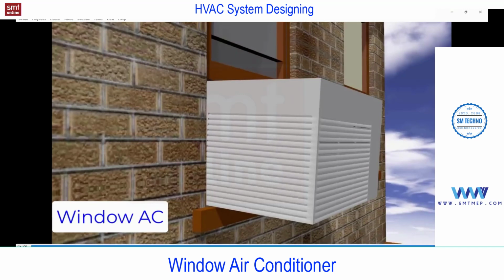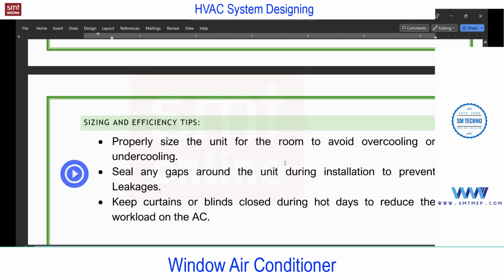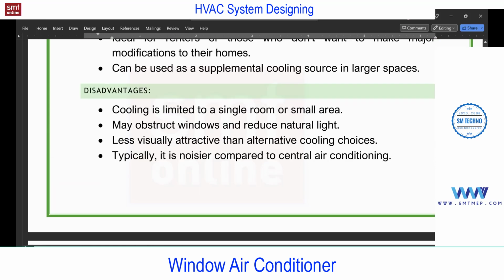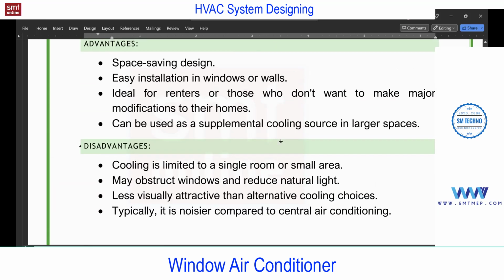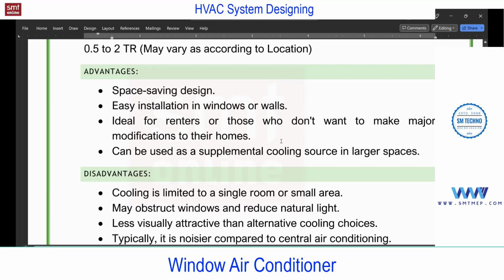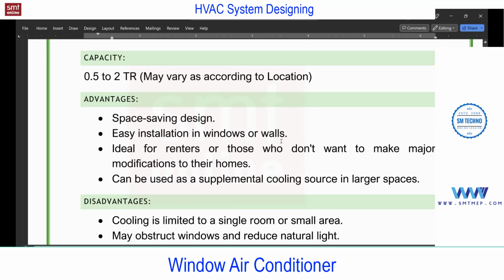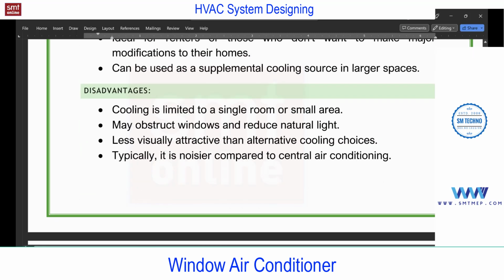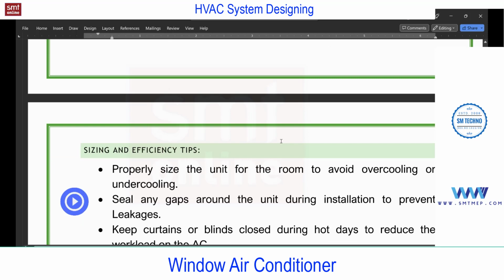Or else, if the water is available on the room side, it may increase the bad smell, fungus and other issues. So hope you got the idea about the window. This is a very small unit and it's like plug and play. There is no installation procedure or list or something. Simply you need to install. Just you need to take care of the inclination, and after installation, you must check for any leakages. And any leakage will decrease the efficiency.